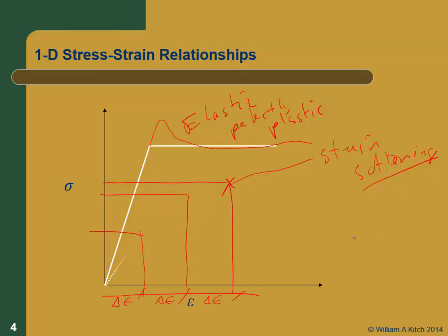And then the third kind of material, whoops, going the wrong way again. This one's actually a little complex because it starts off kind of linear at the bottom and then softens, but then it gets stiffer again. So this is a strain hardening material. It actually starts off as a strain softening material, but in the main part of this curve, notice that as the strain increases, it's getting stiffer. The curve's getting steeper. So this is a strain hardening material. What looks like that? Soil.